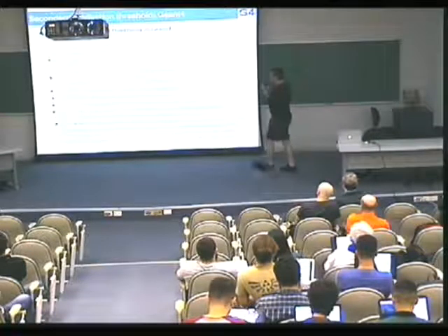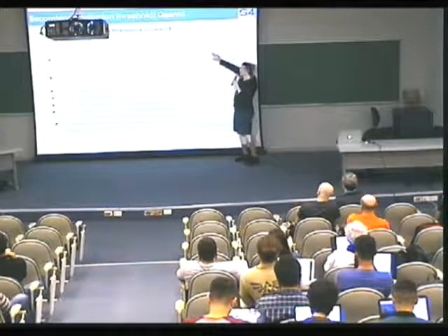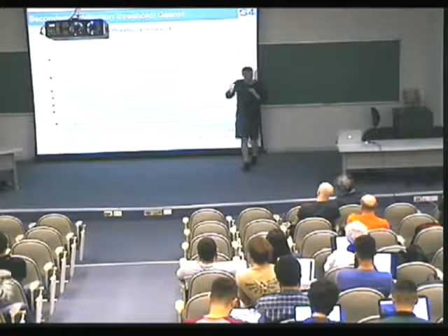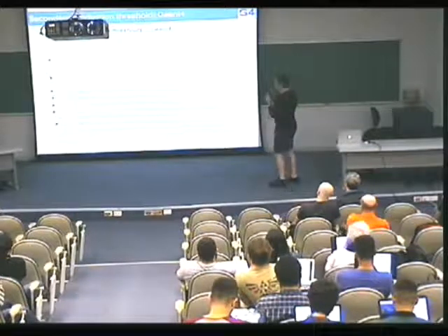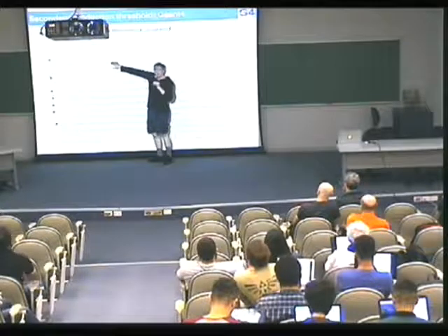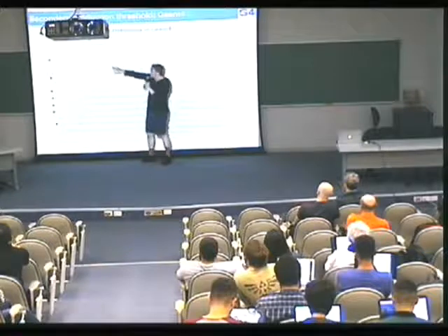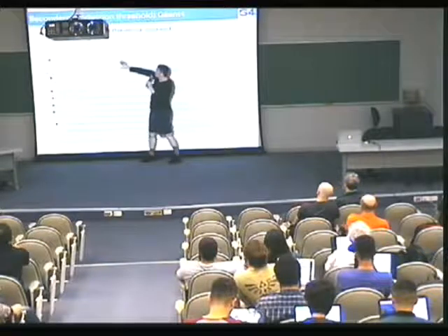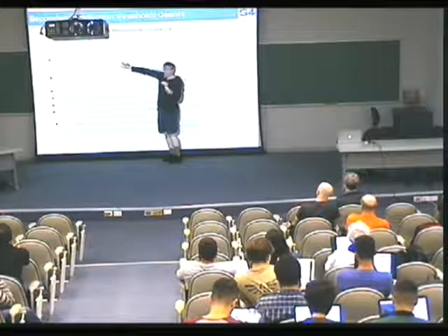And you could see yesterday this interface method in the physics list, the SetCut method. You can use it to set the production threshold in your physics list. Or you can use user interface commands that yesterday you were already trying, like /run/beamOn, whatever. You can set the cut value to any value through your user interface.